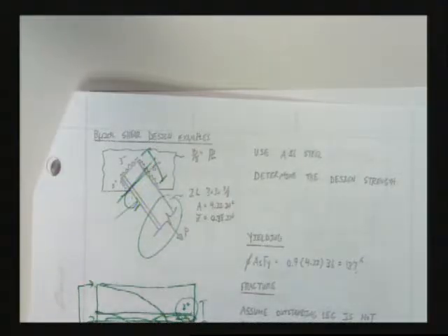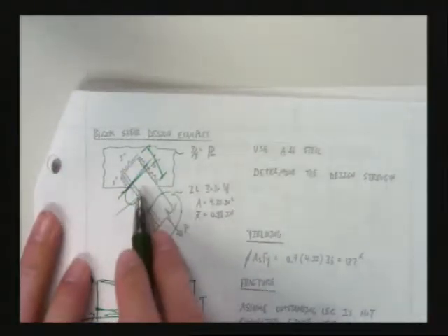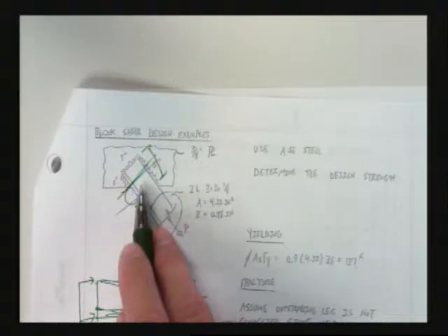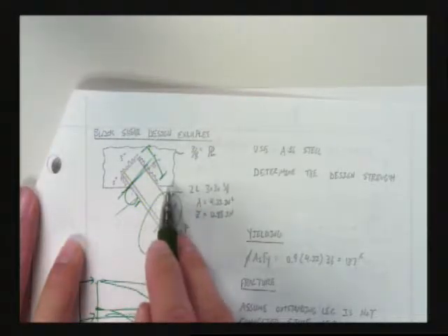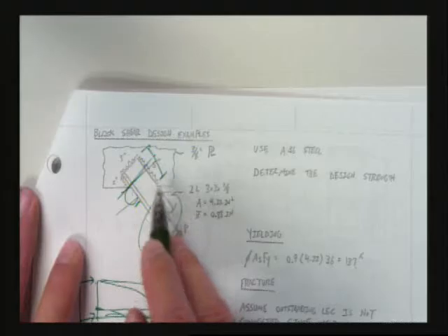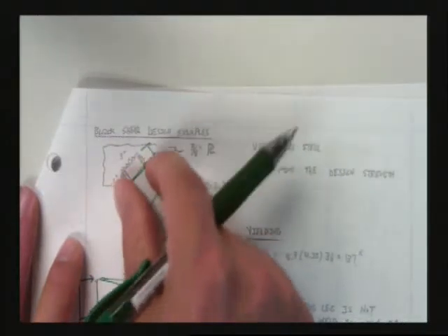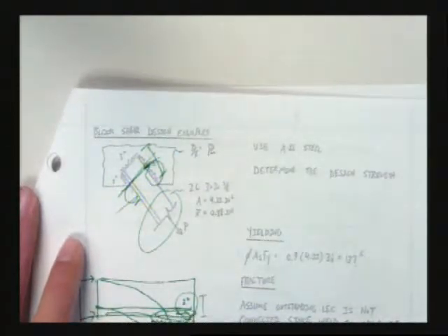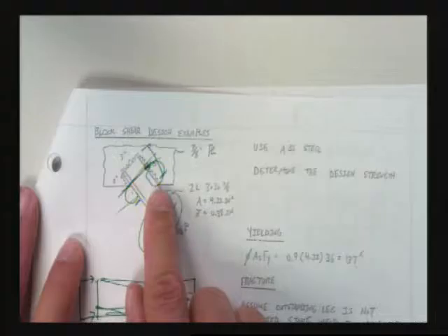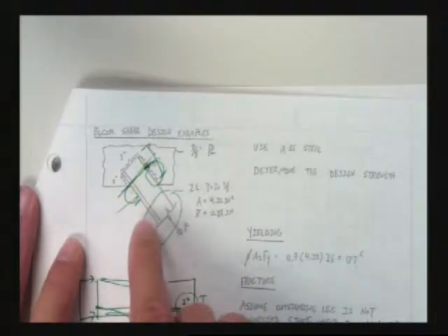The one thing I could say to that is that this is not a weld check per se. This is a cross-sectional area failure check. And when it comes to the weld checks, if you want to not include this weld over here because you're worried about eccentric loading going on, that's up to you, and that's a very good idea. One thing I could say to counter that is that the design and welds already are extremely conservative. And you're probably going to be okay in this type of situation.